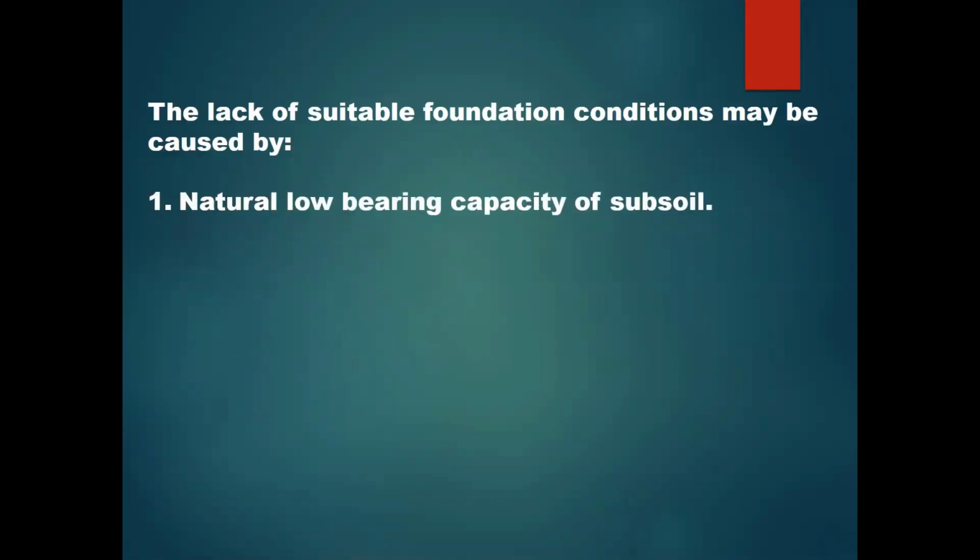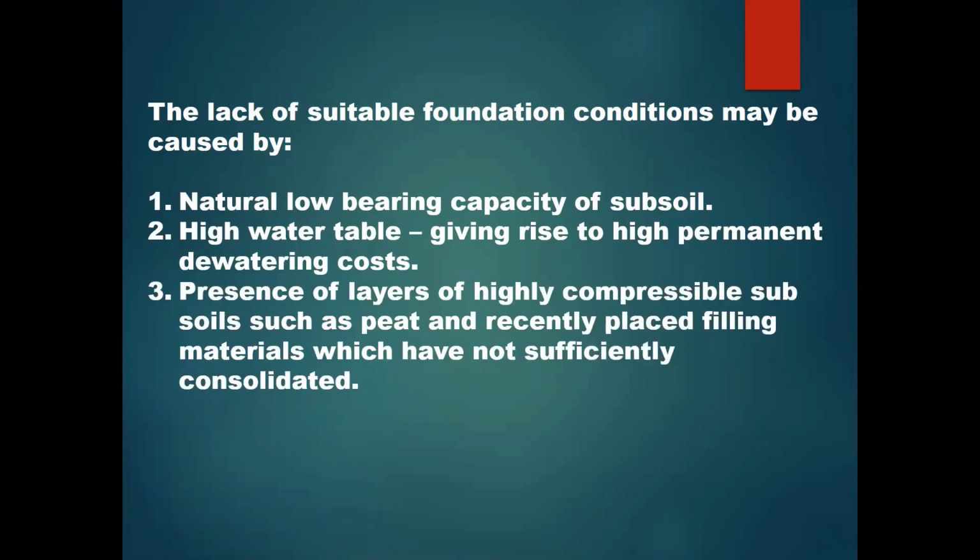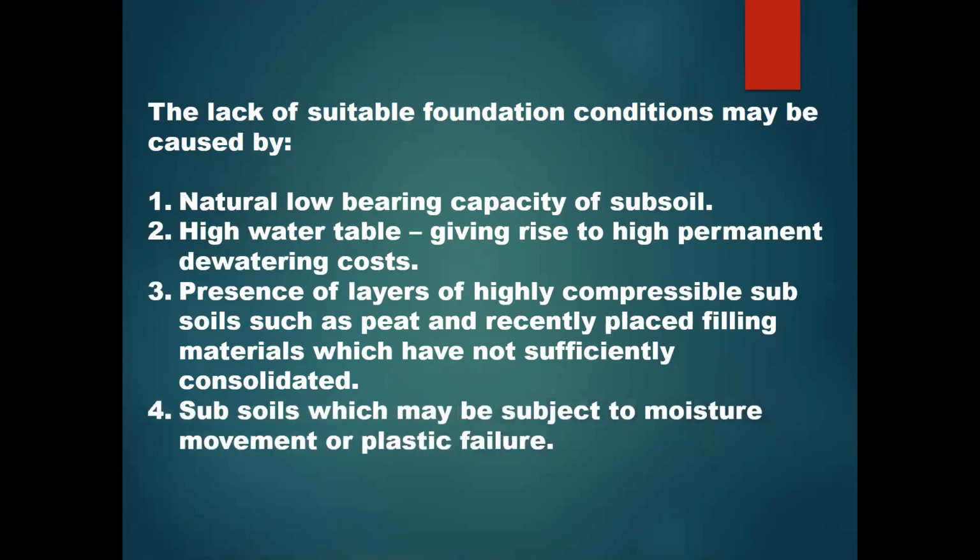So the lack of suitable foundation conditions may be caused by, one, the natural low bearing capacity of the subsoil; the high water table, giving rise to high permanent dewatering costs; the presence of layers of highly compressible subsoils such as peat and recently placed filling materials which have not sufficiently consolidated. Another thing is the subsoils which may be subject to moisture movement or plastic failure.